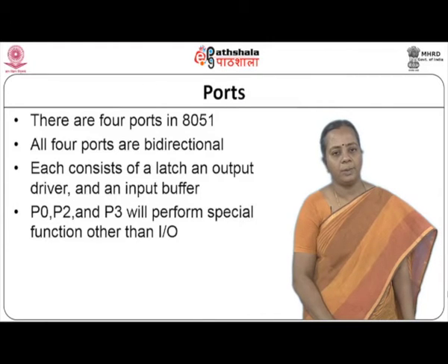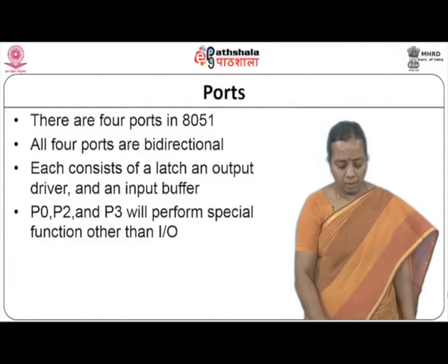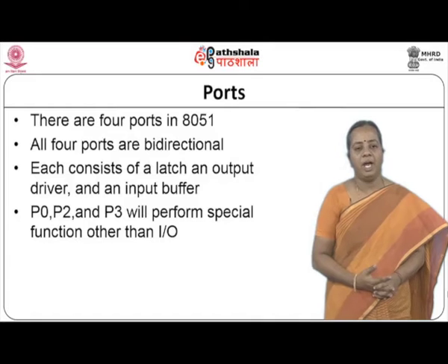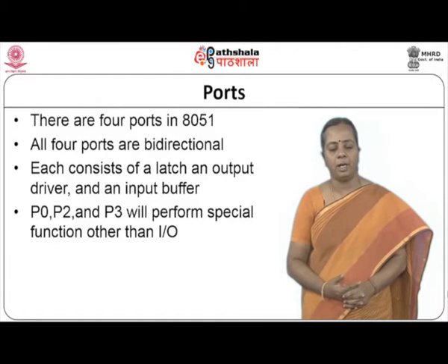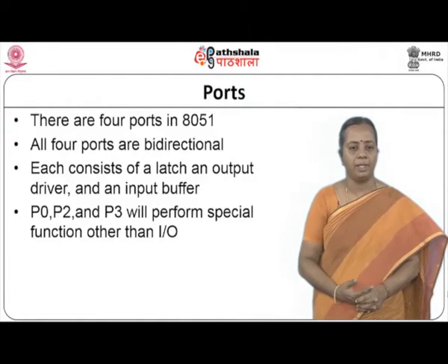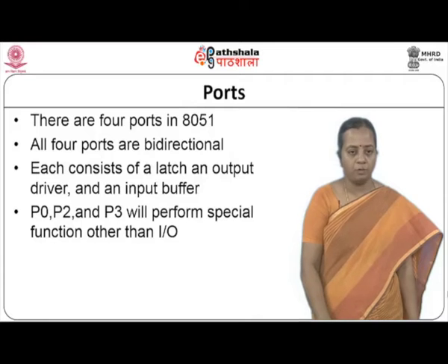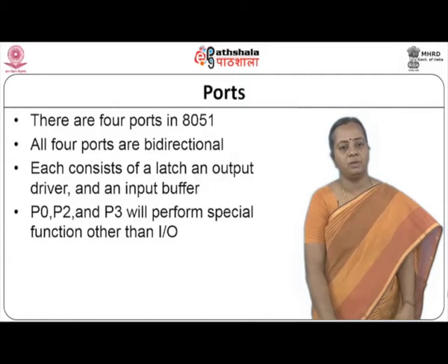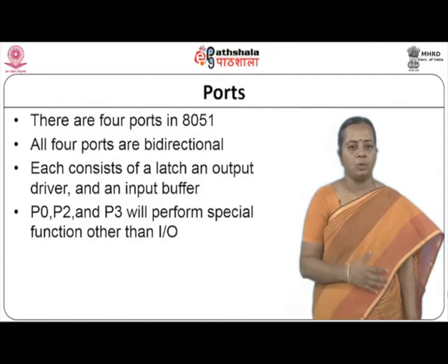Next we will be covering the ports. We have 4 ports in the 8051, which we have seen in the pin diagram itself. These 4 ports can be used for inputting data as well as outputting data.